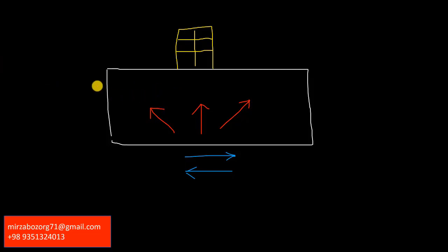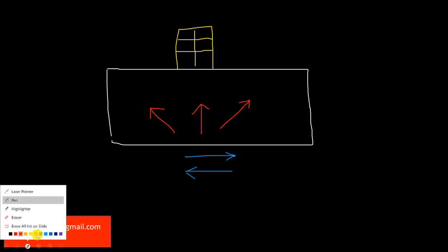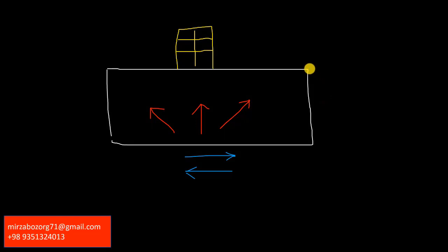So we must define some boundaries here that allow the waves to go out, okay? So here we define quiet boundaries. They are infinite elements.